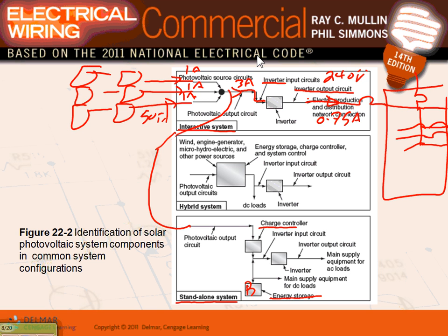So I have a charger. I take the DC from the charger, I charge the batteries, and I can also take a DC load. If I want to run something at 24 volt, I can run a light at 24 volt or whatever voltage I'm running, DC, okay? And I can also have my inverter invert back into 240/120